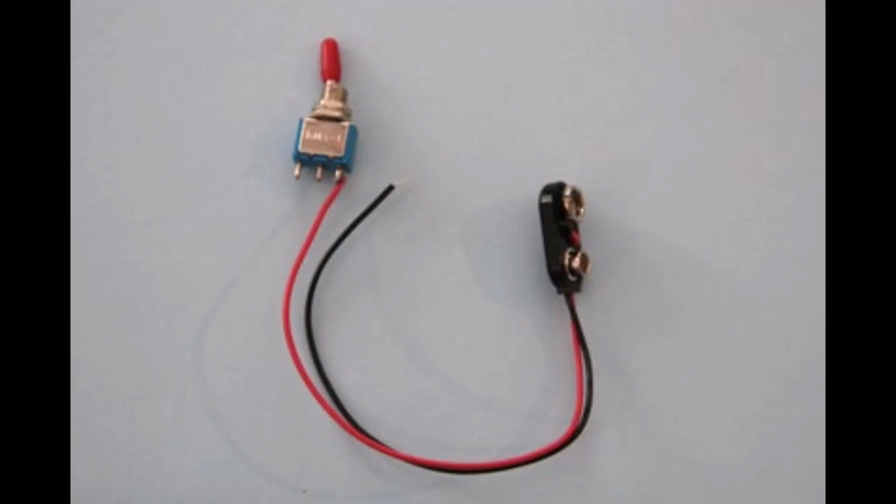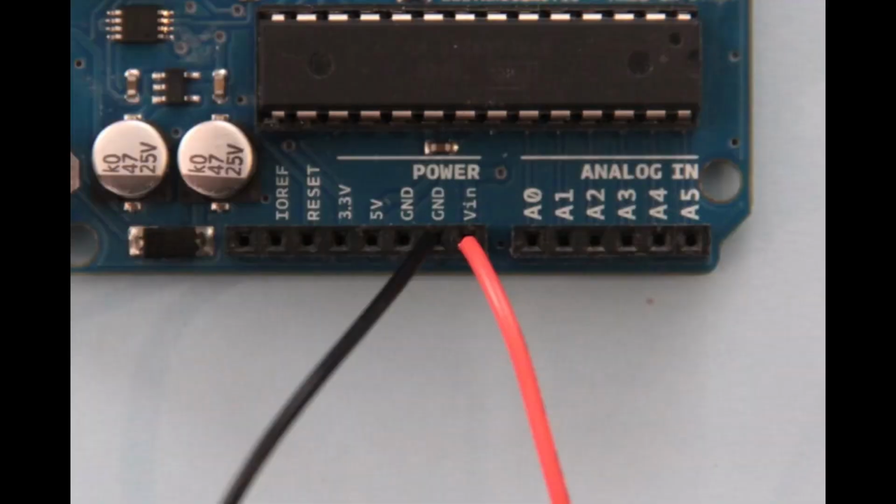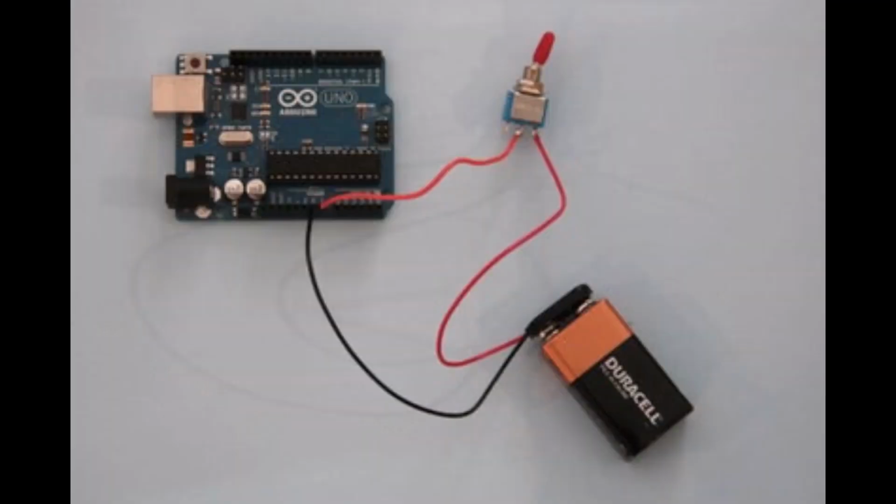Now, if you don't want your Arduino to be constantly plugged into the computer, you can get one of these switches that attach to a 5-volt battery, which you can plug into the Arduino to let it run without the computer. Then, as shown on the screen, you can plug the black wire into the ground and the red wire into the volt. Then you just set it up like this, plugging the top into a 5-volt battery, and then you can just flip the switch on and off when you want to turn it on. You can find all these things online, and you can buy them if you so choose.